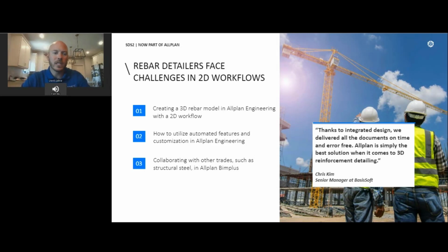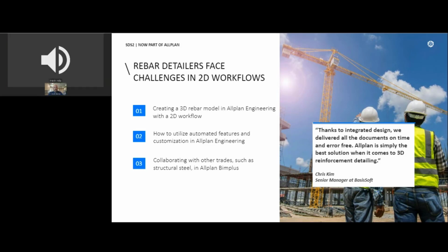A little bit about what we'll see today, Frank. This is your area here with the rebar detailing in Allplan. Do you want to give us a real quick rundown of what we're going to see in Allplan today? Yeah, so we'll see some of the workflows, starting with bringing in a model that David had previously created. We'll bring it into our collaboration platform. We'll then transfer it over to Allplan itself, where we'll author some reinforcement, create some schedules and some drawings, and then pass that information back through the collaboration software so we can all view it together, check for collisions, and do all the things that are necessary when you're bringing a federated model together. And that's about it.